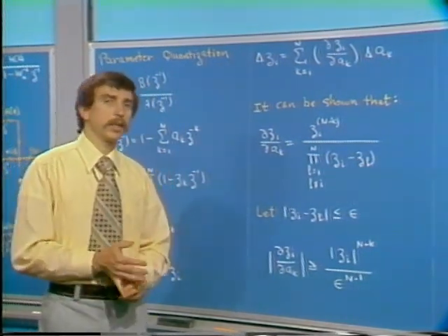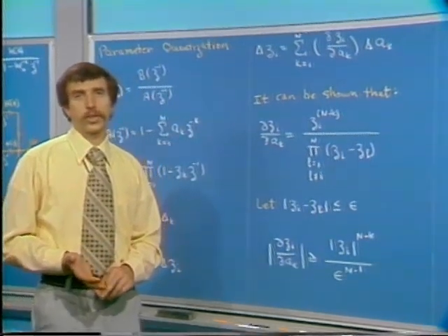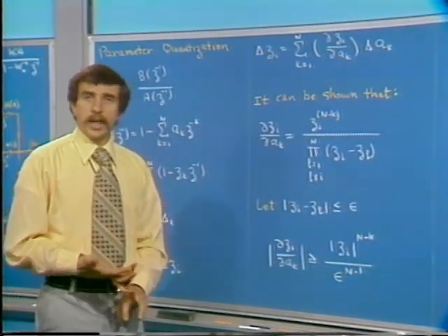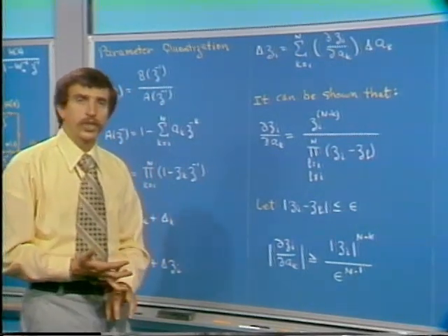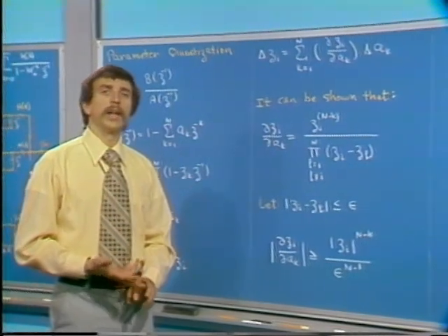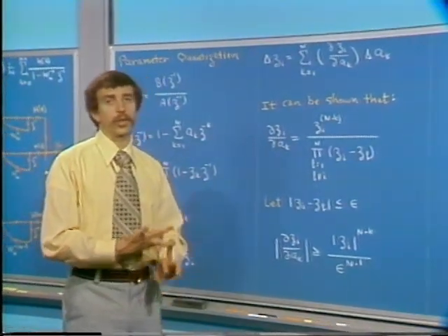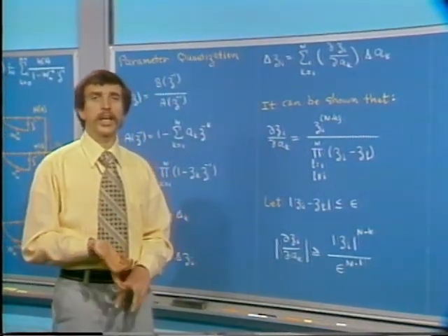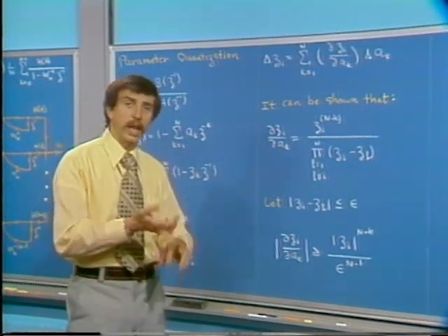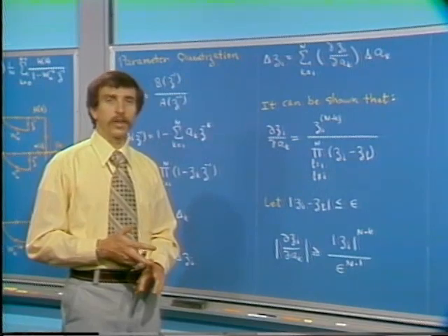It means basically that the direct form structures are the most sensitive, that the cascade form structures are certainly less sensitive than the direct form structure, and the parallel form structure, in terms of the implementation of the poles, has the same type of sensitivity as the cascade form and likewise is less sensitive than the direct form.